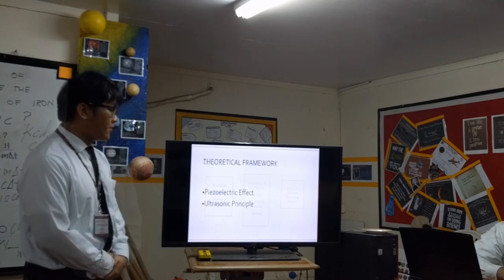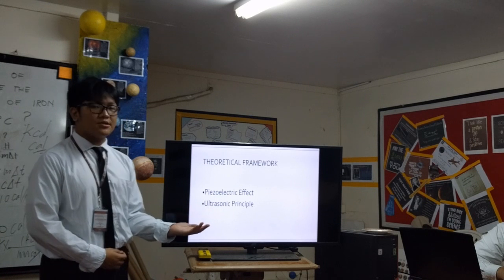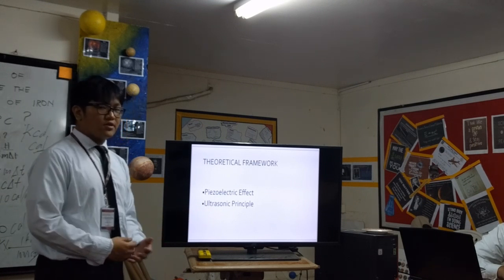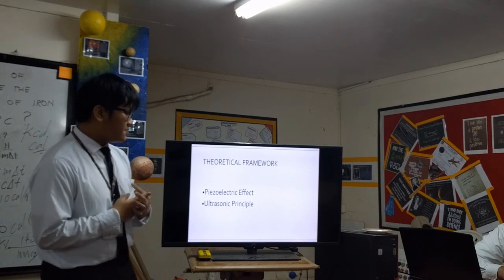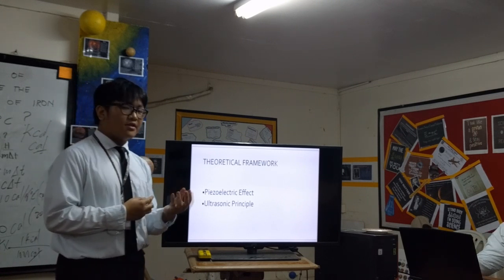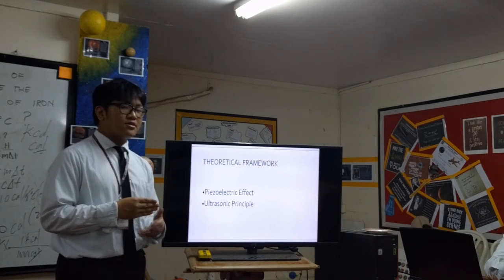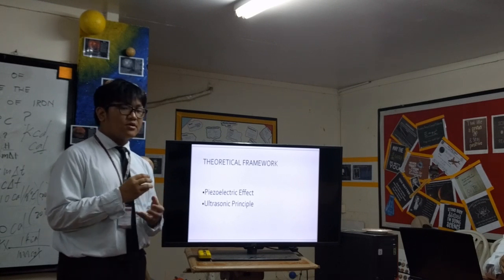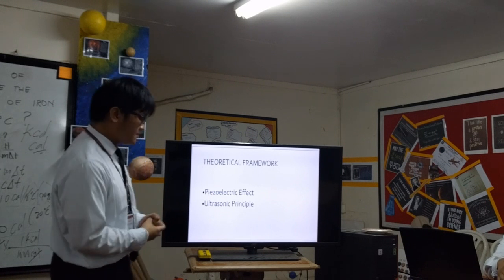So, theoretical framework. Here we have the piezoelectric effect and ultrasonic principle. For the piezoelectric effect, in our sensor we have the transducer and the receiver. For the piezoelectric effect to work, electricity will be conducted to the transducer, and this will cause mechanical stress within it. This mechanical stress will cause the transducer to emit sound waves or ultrasonic sound waves.